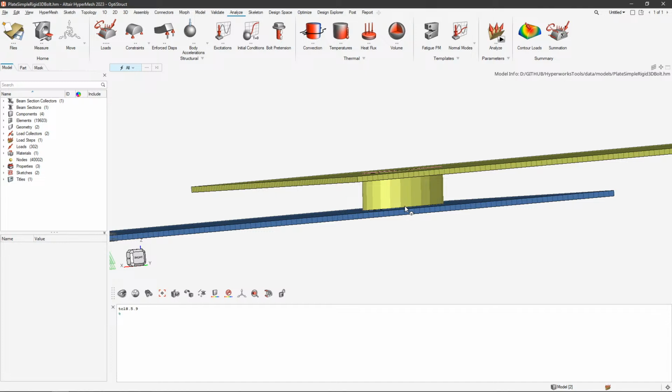I'm not sure about this 100% because bending for sure would not be taken into account, and for sure it would be better to just get the stress values from the 1D bar element. But just for having a rough estimate for a hand calculation, I think it would make sense to have something in the MPC tools toolbox. Not sure what you think about it, but I think there could be a benefit of it.